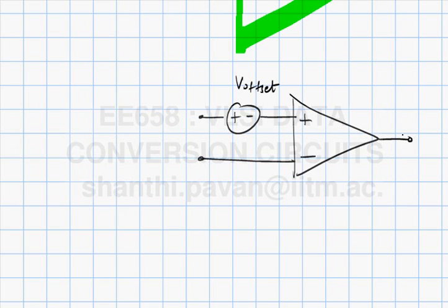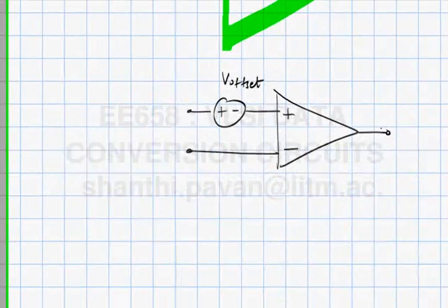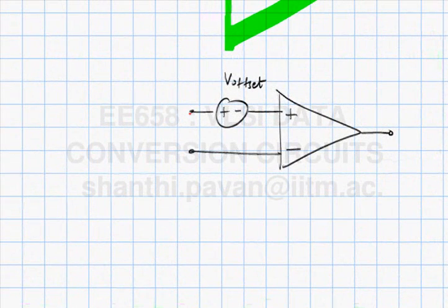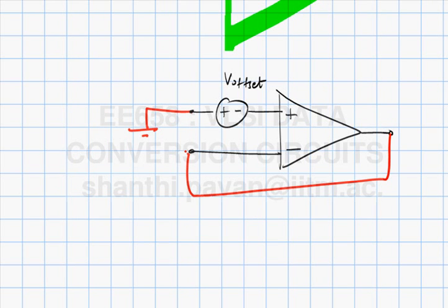So in other words, can you figure out a circuit solution? Okay, one way is to say ground the positive terminal, alright, and do this, correct? Alright, okay, so what is the output voltage now? It is minus V offset. Please go and think about why this circuit makes sense. And I mean, here obviously you guys know the answer, which is why it came out in a flash.